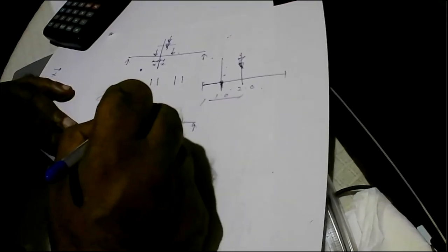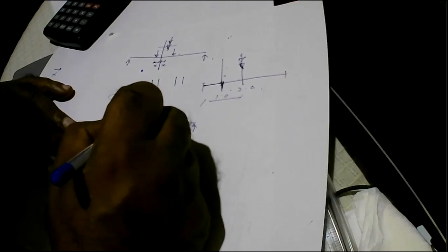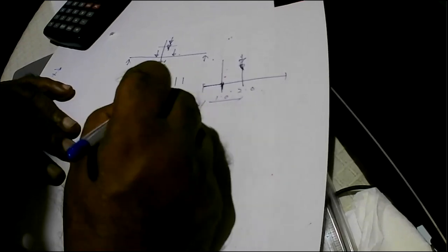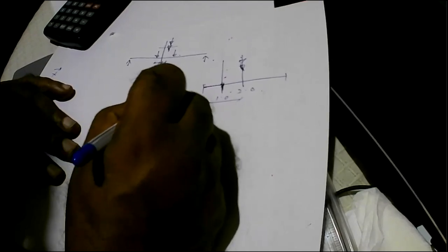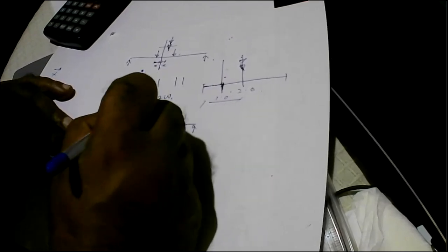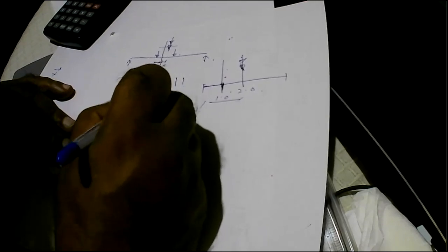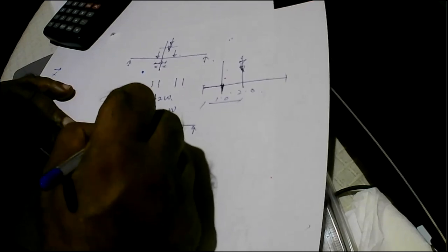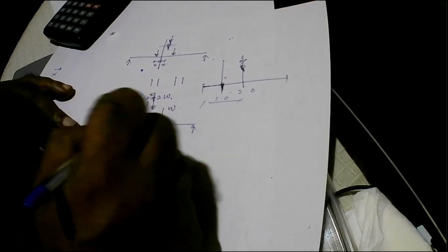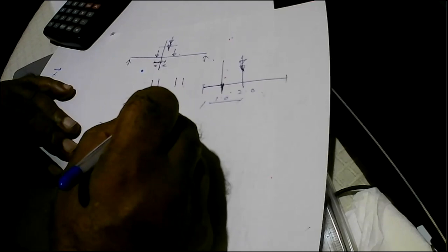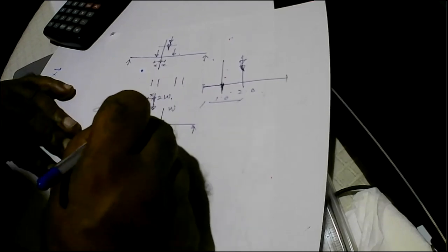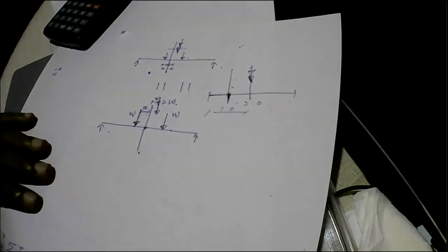If you have two loads, the loading is not due to one axle, but due to two axles. So this W, then what is the resultant? Resultant is 2W. So the theory is, if you want to get the maximum effect, this load is at distance X, one wheel has already passed the center line, the resultant is behind, so that the distance to the resultant and the distance to the load are both the same.